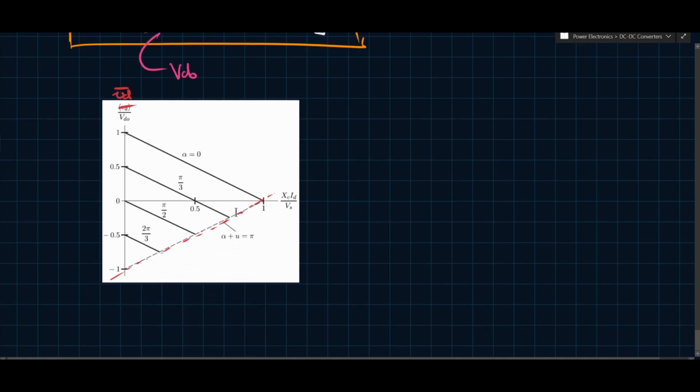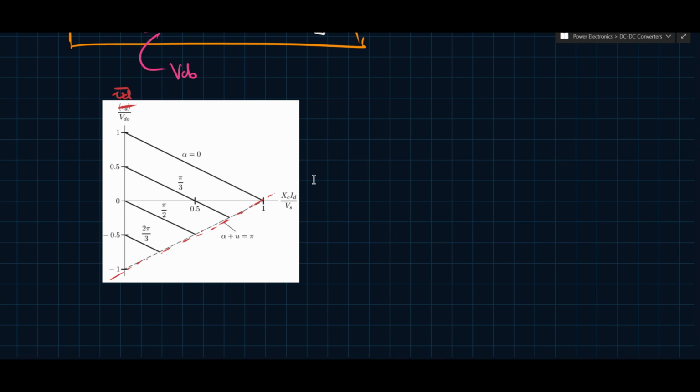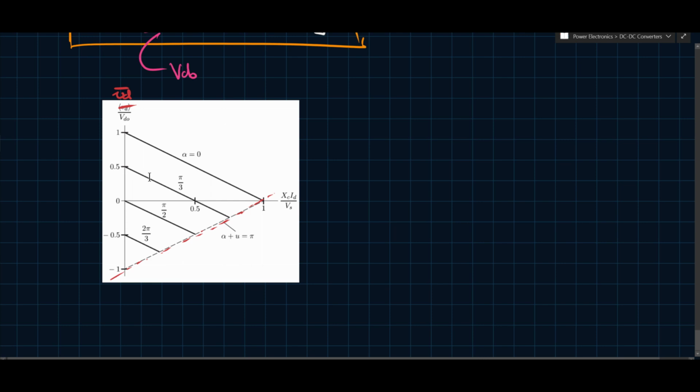And then we have finally established that there is this thing, I think they call it the margin angle. Essentially, it's a limit on how far you can go before you'll have commutation failure. So the current will not commute entirely from one branch to the other. Again, it might be something desirable. It is in certain cases. It's not necessarily a bad thing. But for standard normal operation, it's best to operate within these regions here.